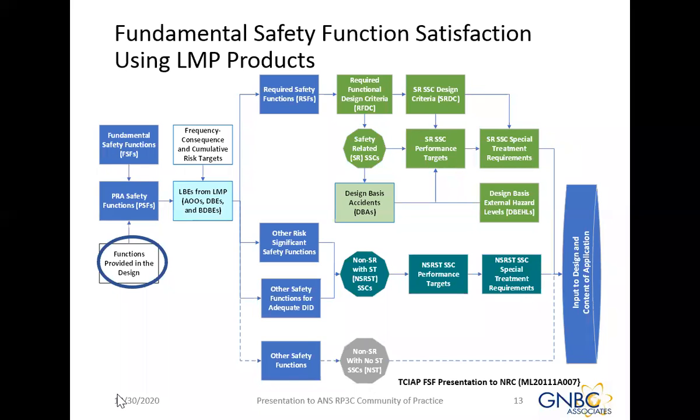One point I want to make, which is why I've circled the functions provided in the design, there's a very important step in the early development of the design to do a HAZOPS or something equivalent to a HAZOPS. And that step is really where you catalog all the potential challenges to the design for both safety reasons and other reasons, as well as align all of the functional outcomes of having something that makes something that's of value to the owners and the public.